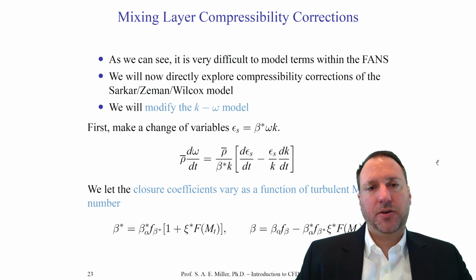So some CFD codes use these types of compressibility equations and corrections versus trying to move forward through the whole RANS closure processes and implementation, which is of course much more mathematically rigorous and robust and creates better predictions sometimes, if not usually, relative to the modification of the base equations such as k omega.